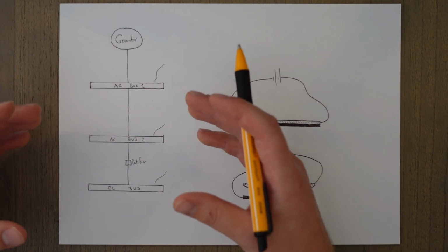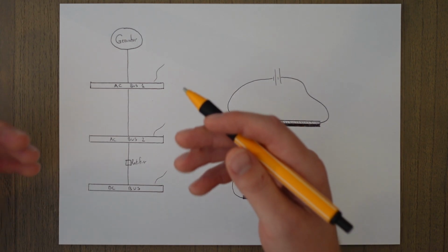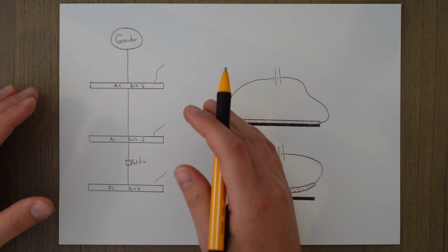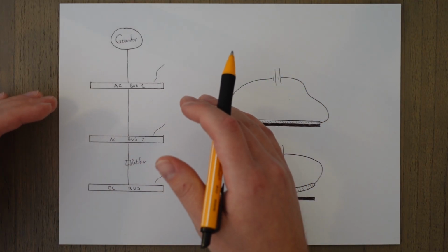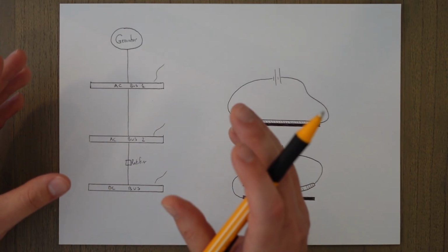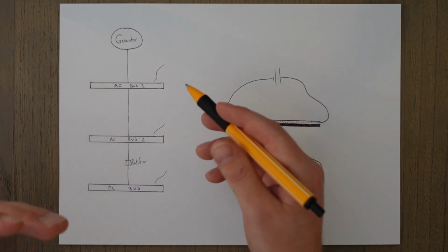We can essentially group them into different categories based on how important they are for the safe conduct of flight. Then if we have any problems to do with the electrical system on board, then we can ditch loads of systems at once. Which system is assigned to each bus bar is something that a manufacturer will know, and it differs from plane to plane.